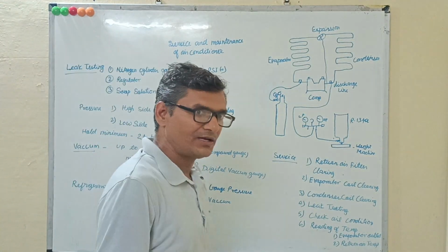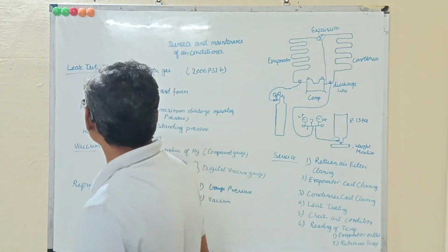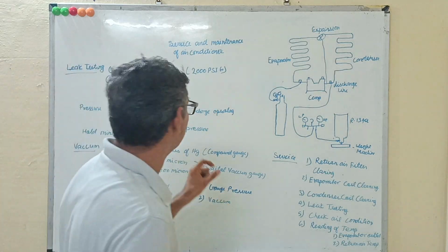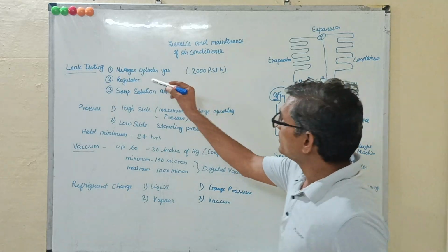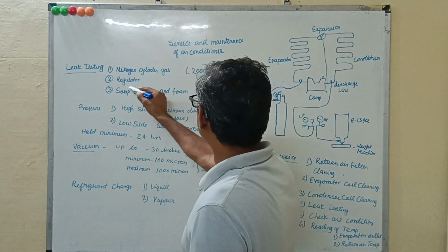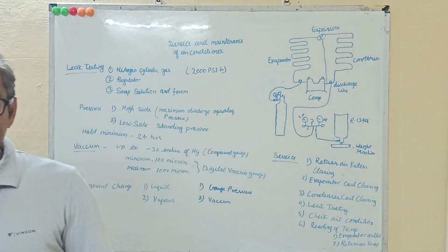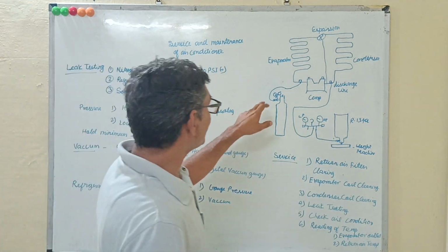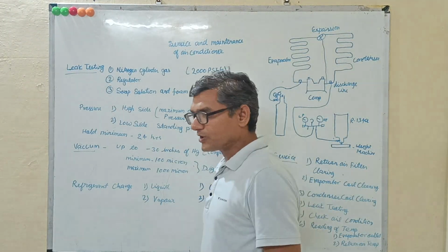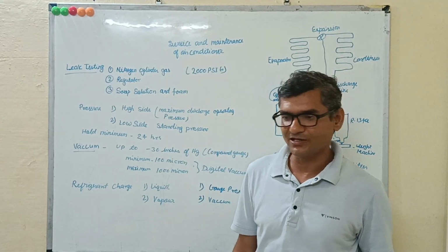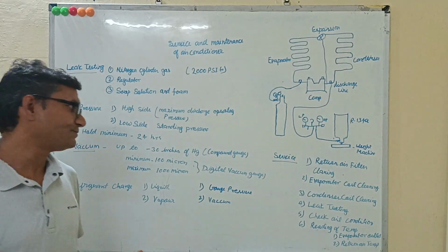Okay, then first we will recover the gas and store it in the cylinder. Next we have to use nitrogen. The nitrogen cylinder must be kept in a vertical position, and a regulator is compulsory, because we are not charging nitrogen directly. A full nitrogen cylinder is a minimum of 2000 psi, and 2000 psi is much more. Accidents may be possible if we are not taking care.